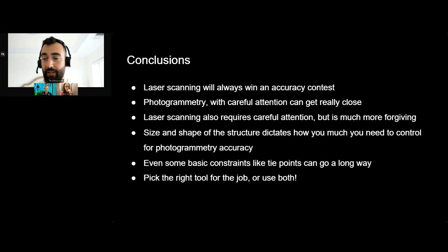If it is a vertical structure like that bridge or that house, and you do want to use controls and known point coordinates, I would probably use something like a total station, right? That opens up a whole other instrument and a whole other set of expertise. Maybe bring a surveyor to do that for you, but it definitely is possible. There's always a way to set controls. It's just a matter of doing it in a way that the measurement is going to be accurate itself, because there could be error in that control as well if it's not done correctly.